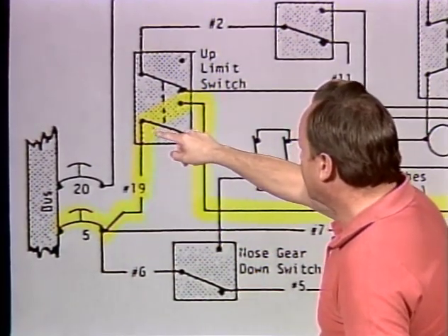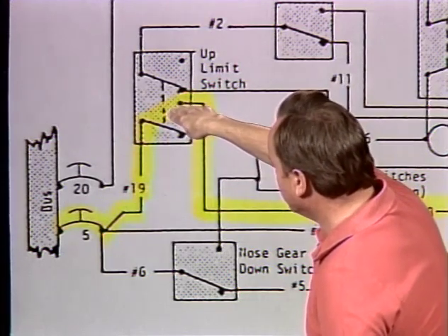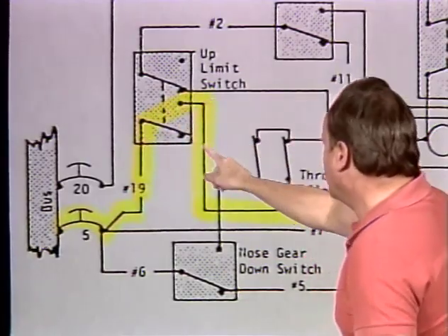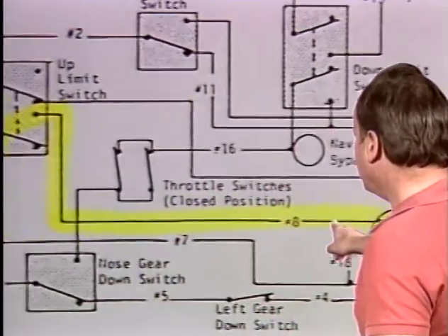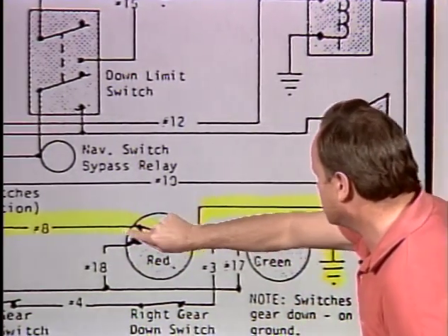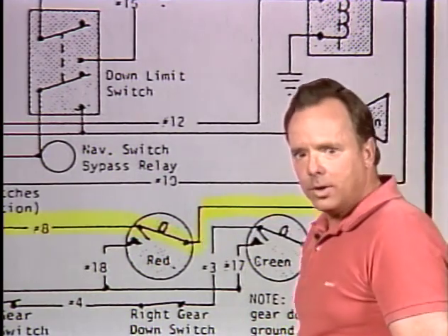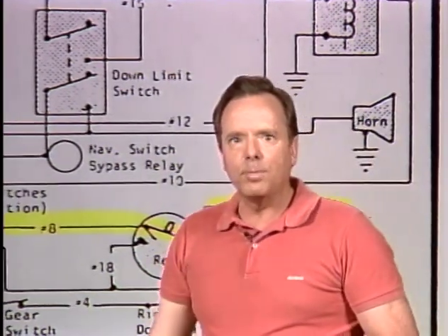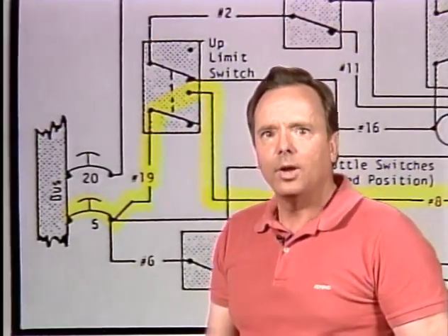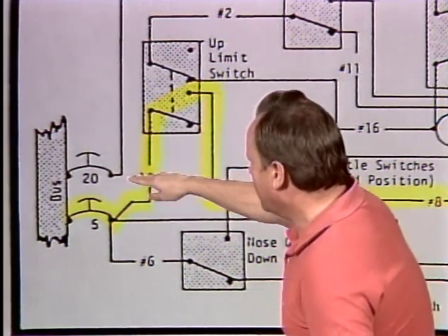And if you have the landing gear retracted, this switch is in the up position. And so now you have this switch in the up position, and we go through wire 8. And wire 8, as we said earlier, will light this red light because it's connected right to the red light, and then that goes to ground. So you can see that wire 8 is our path. Now let's go back and make sure that we've answered the question. And what you need to know is if there is an open in wire 19, none of that will happen.